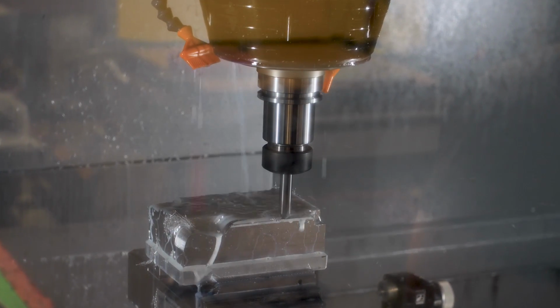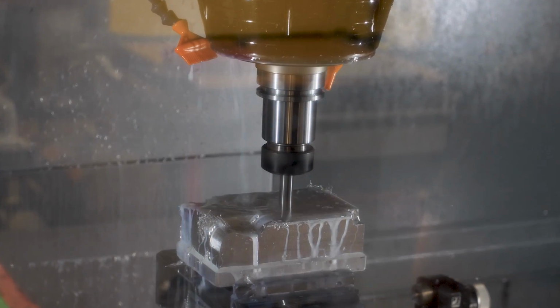Lastly, we have chamfers. Chamfers are created by machining angled faces on the edges of parts. Countersinks are technically chamfered holes. Chamfers can exist anywhere two surfaces meet at a sharp angle. They are often used to make corners of parts less harsh and to allow parts to mate up easier.